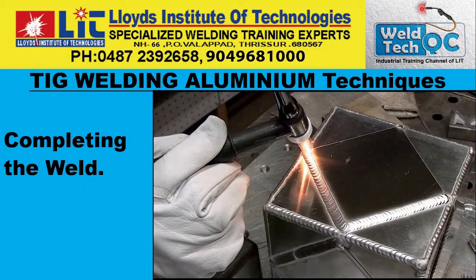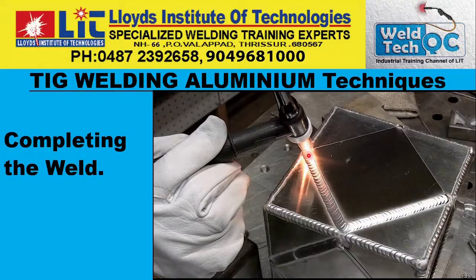Similarly, completing the weld is also very important. The manner in which the arc is broken at the end of a weld is very important. The best method for eliminating craters is to finish welding with a decreasing current. This technique, frequently called decaying arc, is usually done by means of a hand actuated control switch. So with the latest machines, this function is inbuilt and easily adjustable. So ensure to do that.